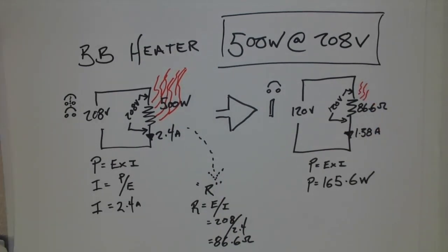And so this can be a common problem when people do panel changes for electric water heaters in residential installations, and they forget to connect the water heater to the rated 240 volts and instead accidentally hook it up to 120, and you don't get half the amount of power. You get a substantially lower amount of power, right? What you do is you divide that 500 watts by 3. It is 1/3 the power of the original. So it makes a substantial difference in the length of the hot water shower you can have.